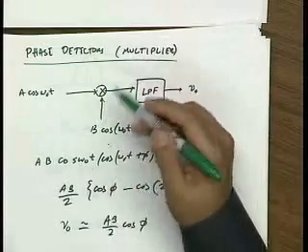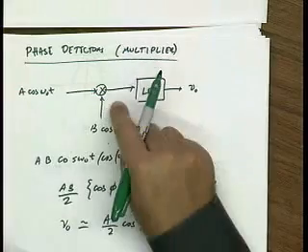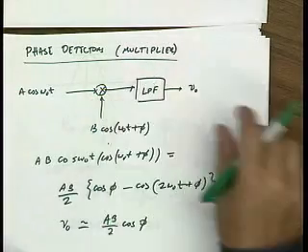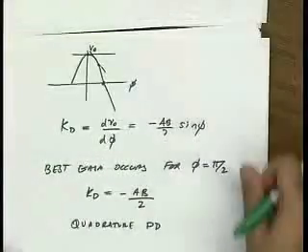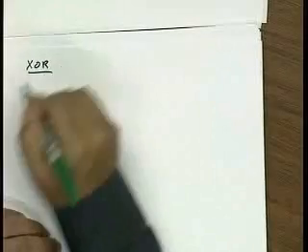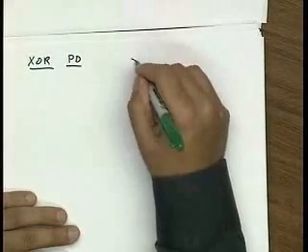So these circuits really can be purely digital. There's no reason to use complicated analog circuits here when you can build really cheap digital circuits, okay? And by cheap, we're talking really cheap. For instance, you can even use a simple XOR gate as a phase detector. So how does that work?